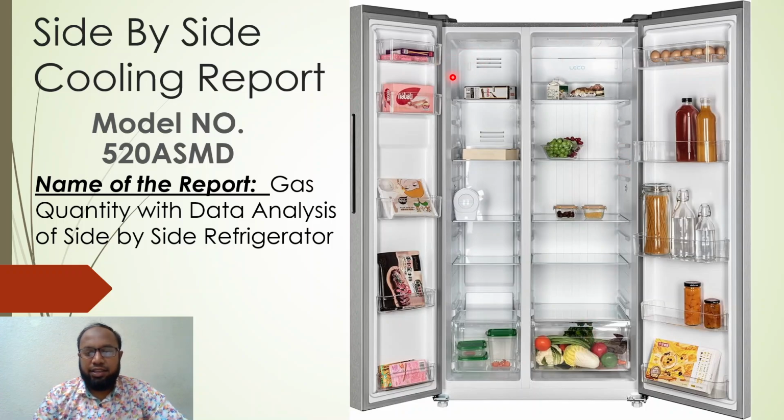Here we are setting the freezer temperature at minus 18, within a range of minus 15 to minus 22 degrees centigrade. And this is the refrigerator chamber, where we can fix the temperature range at 2 to 8 degrees centigrade. In our case, we are doing a load test of the refrigerator with a performance test.